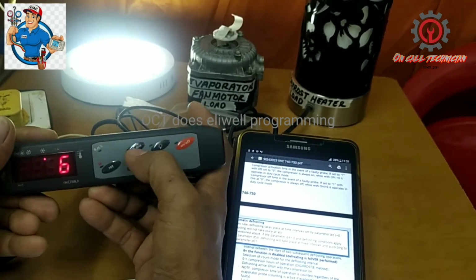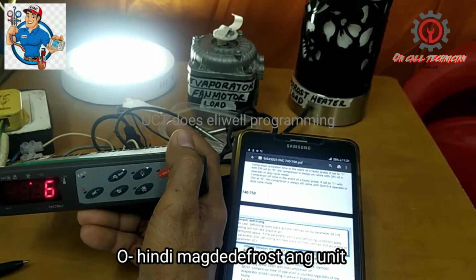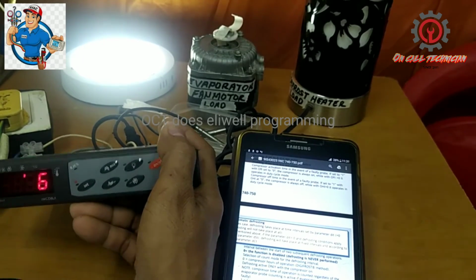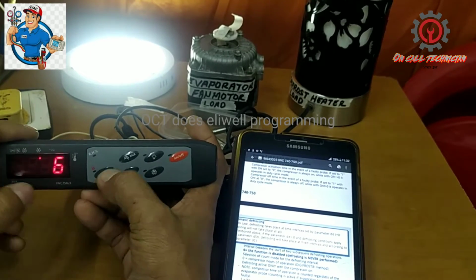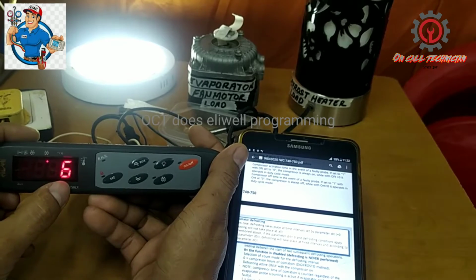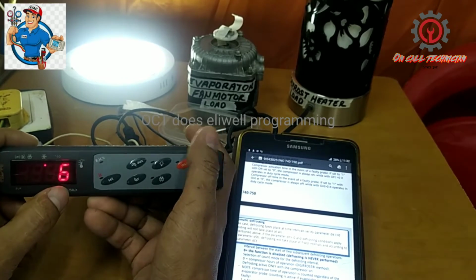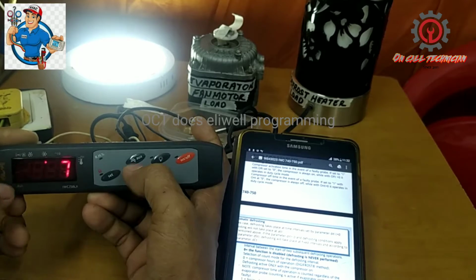Now this 6, the defrost will defrost every 4 hours. This default value is your defrost will activate every 4 hours. You change it to 7.